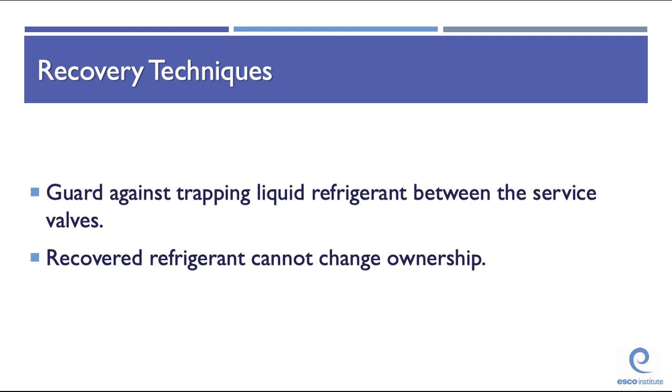After completing the transfer of liquid refrigerant between a recovery unit and a refrigeration system, you should guard against trapping liquid refrigerant between the service valves. Recovered refrigerant may not meet ASHRAE standards for virgin refrigerants, and therefore can only be reused in the same system or another system of the same owner. Recovered refrigerant cannot change ownership.